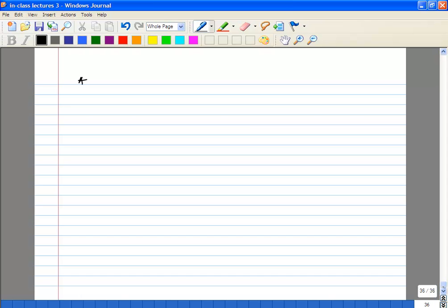So let's say now we want to improve your IIP2. How do you improve your IIP2? You want to remove, yeah, exactly. The number one thing is you want to remove your second order, fourth order and so on. The best way to do that is go differential.